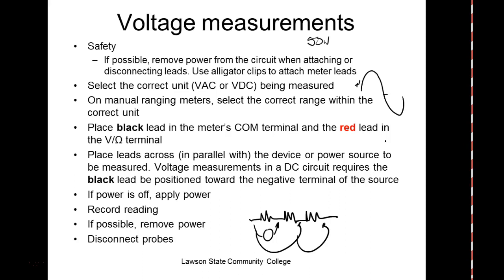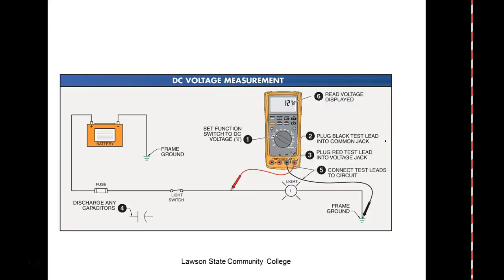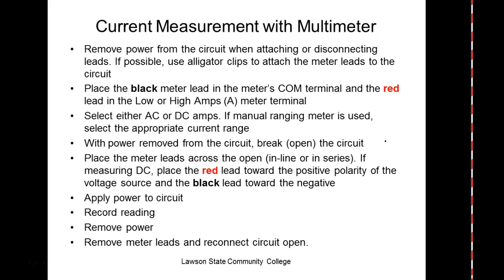And we refer to it as a ghost voltage. But it's going to be a lot less than the voltage you're trying to measure. DC, if you turn power off, guys, you're going to measure 0 volts. So this is an example of the way we connect the voltmeter, right? Current meter, we always put a current meter, or an ammeter, in there. We always turn the power off.